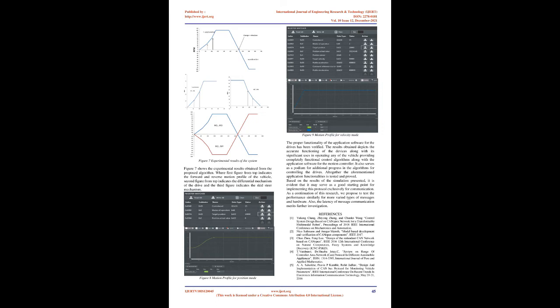The key notion in controlling the multiple motor drives using a single embedded controller is based on the different profiles supported by the CANopen protocol, that is position, velocity, and torque profile. All the tasks are performed once the initial settings are carried out for establishing the network interface between the controller and the motor drives. The software flow for the network interface is as shown in Figure 3.